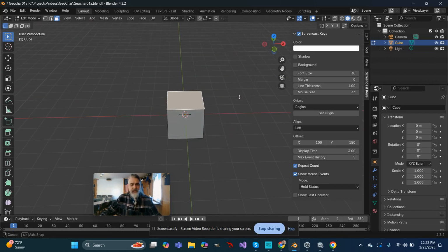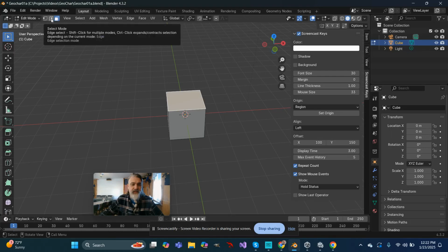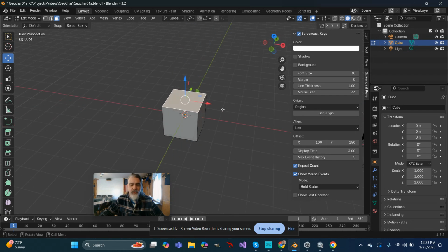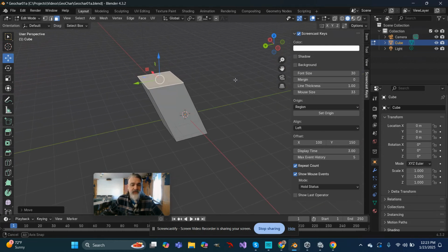So let's take a moment to discuss manipulating this object. So just like in the last video where we were able to manipulate the object in scale or position or rotation, we can do the same thing to the faces, the edges, or in some cases the vertices. And we can do it in pretty much the same way. So if I go to my buttons on the side with this face selected, you can now see that a gizmo showed up similar to the gizmo in the upper corner, and I can simply grab and move this face around, and the whole object sort of adjusts with it.